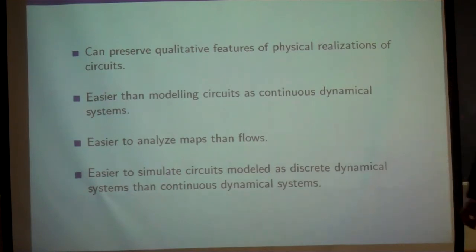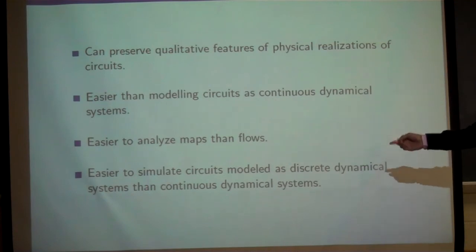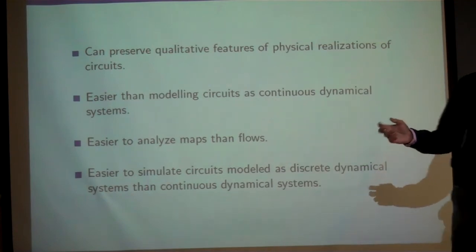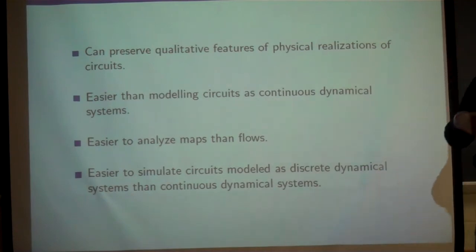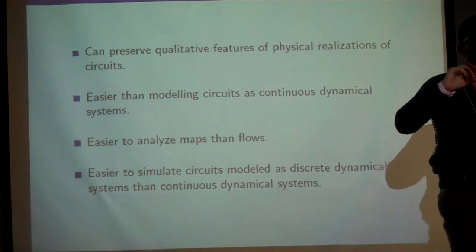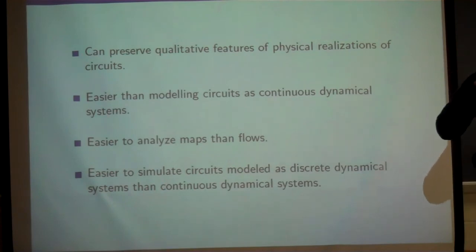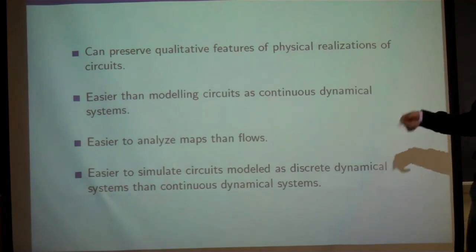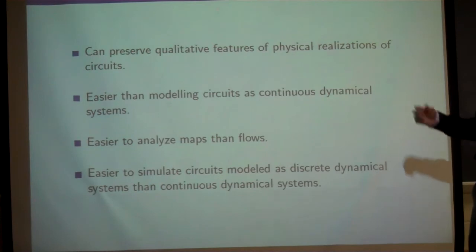maps of flows. And it's certainly easier to simulate these circuits using difference equations rather than differential equations, because with differential equations we would have to do Runge-Kutta or some sort of finite difference scheme. But with these difference equations, we just put it into MATLAB, we iterate the difference equations, and that way we simulate these circuits. The difference equations are just going to be voltages, and we just iterate that.